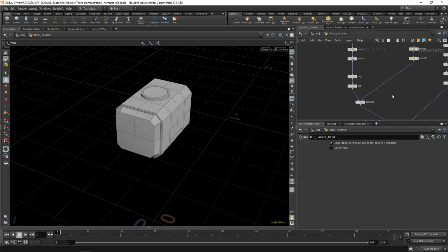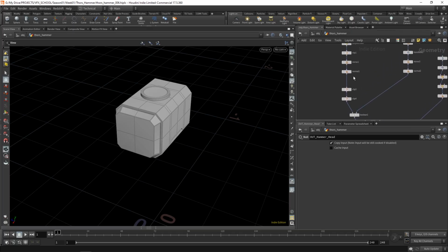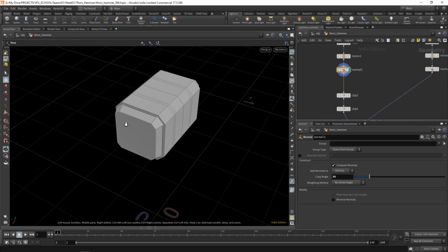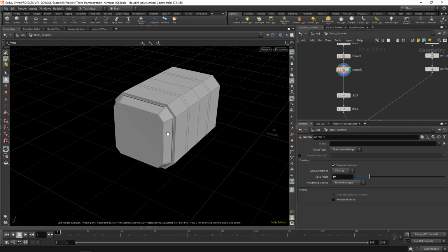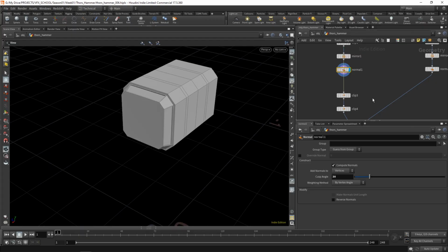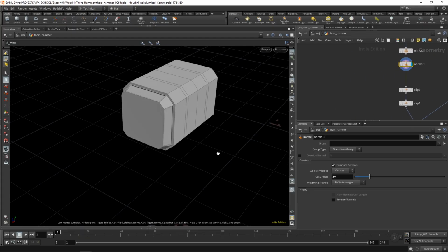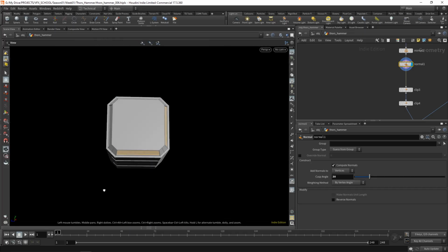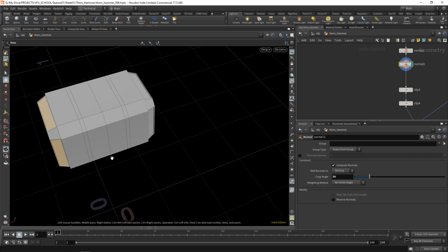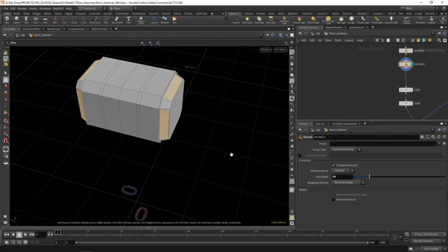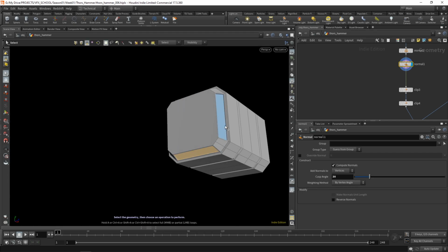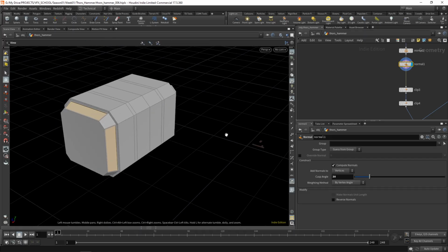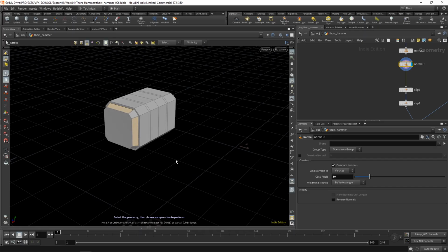We can actually grab those faces easier if we go all the way up here while they're still not divided, and it's easier for us to select those. So let's grab them there. I'll type S, making sure I'm in primitives, and I'm going to select these 4 on this side and the other 4 on the other side. Now that they're selected, I'm just going to be pressing delete.